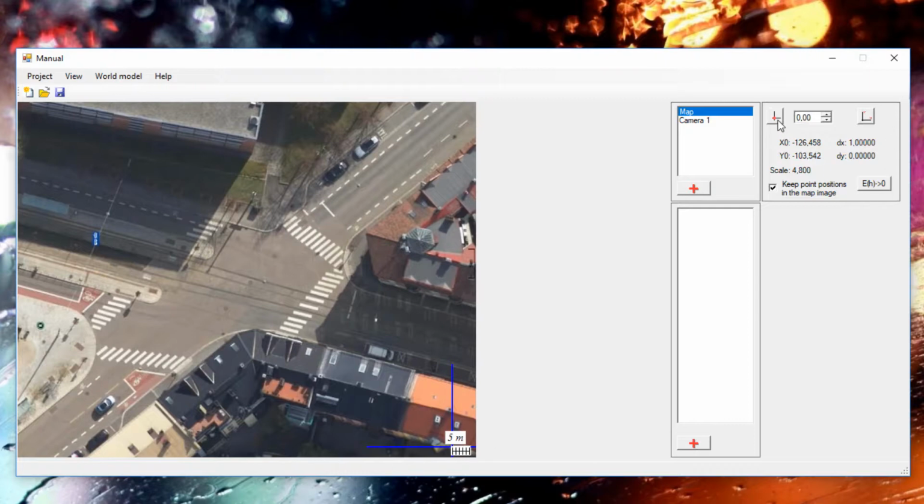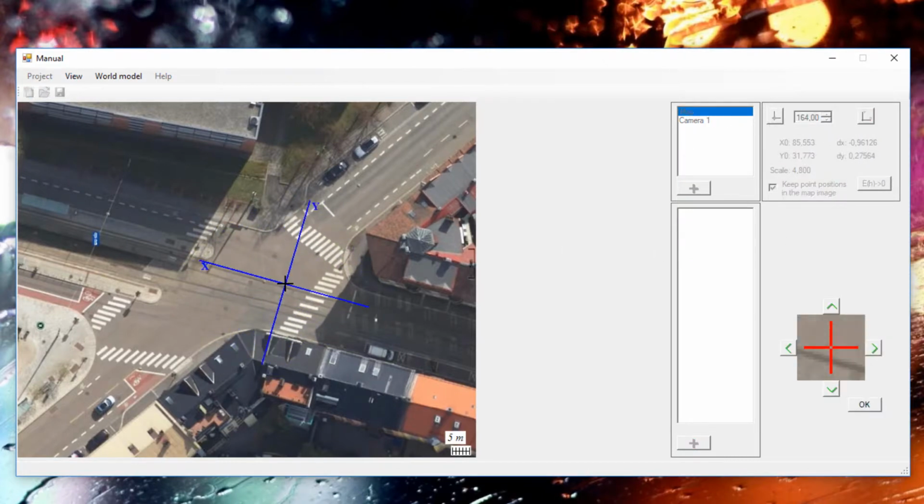But we can quickly move that, press there and there. Worth noting is that when you import this into T-Analyst later, the car is always going to drive towards the X. So place it the way you want to have it. I'm going to rotate mine like so. Okay, and that's that.